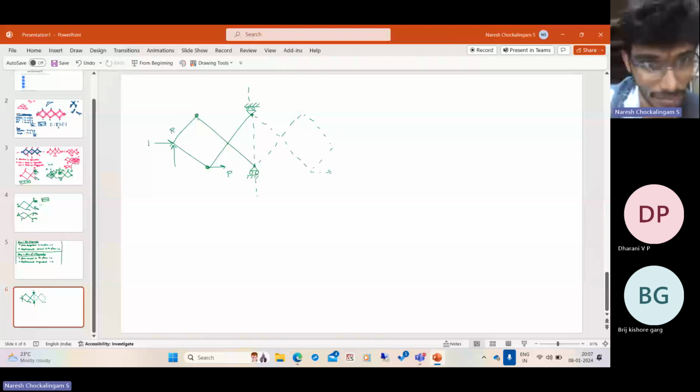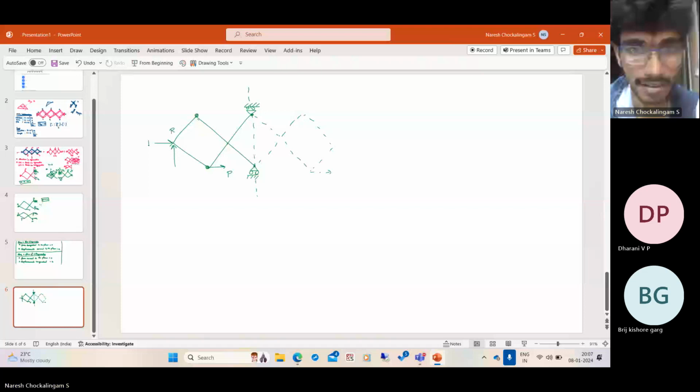What will be the horizontal force here? It is anti-symmetric, so it will just be flipped. So it will be in this direction. If it is symmetric, both will be directed towards the plane of symmetry. Since it is anti-symmetric, one of the reactions is towards the plane of symmetry, and the other reaction is away from the plane of symmetry. Just exactly similar to the forces. Here the forces towards the plane of symmetry, forces away from the plane of symmetry.